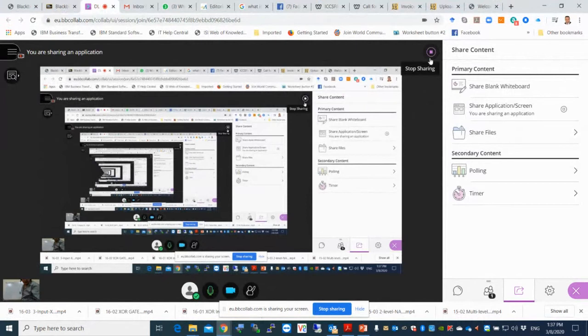Okay, so the typical steps for design. Number one, as we mentioned, identify the inputs and outputs and verify they are binary. Step number two, validity. Step number three, K-map. Sorry, this is something that we missed here.